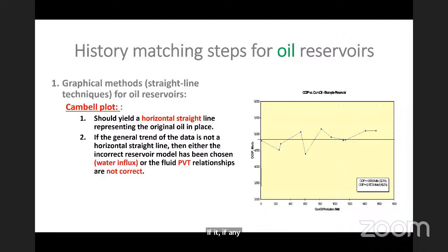And as I told you, if you have any discrepancy, you have to challenge back your data and or your PVT. For example, on the model I showed you, I told you, yes, I have to go back and see, or start a new model, because I may have collected PVT data which is not the PVT of the reservoir, or I collected production data which is not related to the PVT of the reservoir. So no harmonizing, no matching, which may result in something like this. Okay.